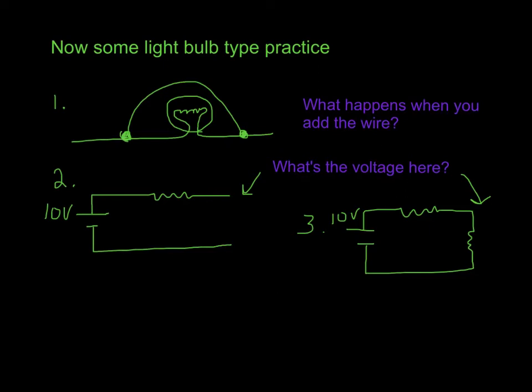This doesn't happen in real life. If you load a circuit, the poor pump man in the fluid flow analogy isn't going to be able to keep up, and the voltage is going to go down. So even though your battery gives 10 volts, if you put on too small of a resistance, you short it out, that 10 volts is going to go down towards 0 because you're just going to draw too much current from it. We're not assuming that here.